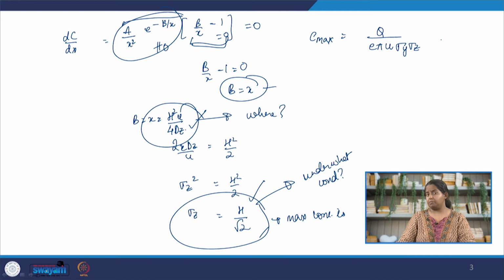If it's a stable environment, this won't work. If it is very unstable, this won't work. Only for two kinds of atmospheric stability will this system work. Also, all other assumptions that we made in the Gaussian plume model are also true. So wind can't be too slow. This is only valid for short durations of time and in flat terrain, because the wind velocity will change over time.